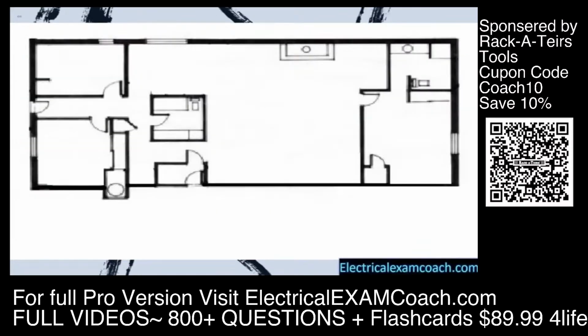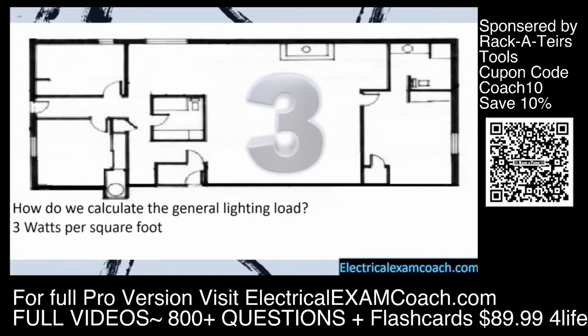The first question we have to ask is, how do we calculate the general lighting load? Are we going to calculate it per receptacle outlet, per lighting? Do we have to count them, add it all up? Thankfully, no, they've made it very simple. We're going to calculate it at 3 watts per square foot. So for all of the general lighting and all of the general receptacles, all we have to do is take the square footage of the dwelling unit and multiply it by 3.